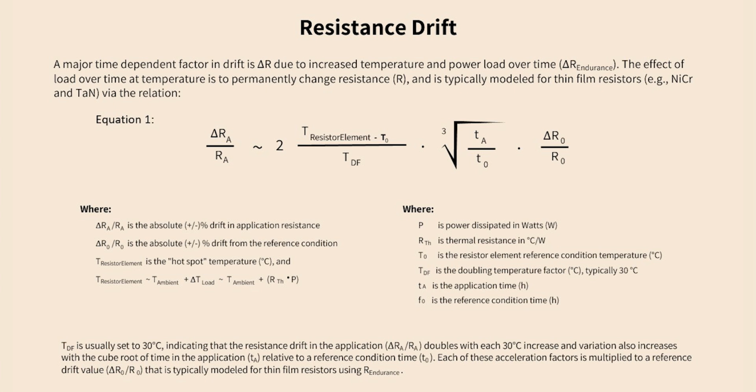This model emphasizes the importance of managing temperature and power to minimize resistance drift. Proper thermal design and power derating can significantly enhance the stability and longevity of thin film resistors in high-performance applications.